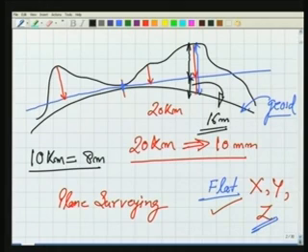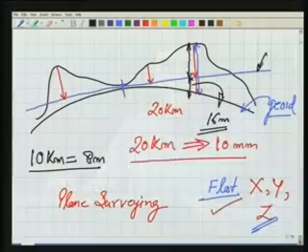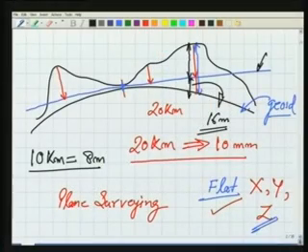This is too much. A small town could be 10 kilometer, and we are introducing an error of 16 meter in that, if we are measuring the heights from the horizontal plane. So what do we mean by this? We mean that we can use a horizontal plane, or consider our earth to be flat, for making a map which is only plotting x and y, not height.